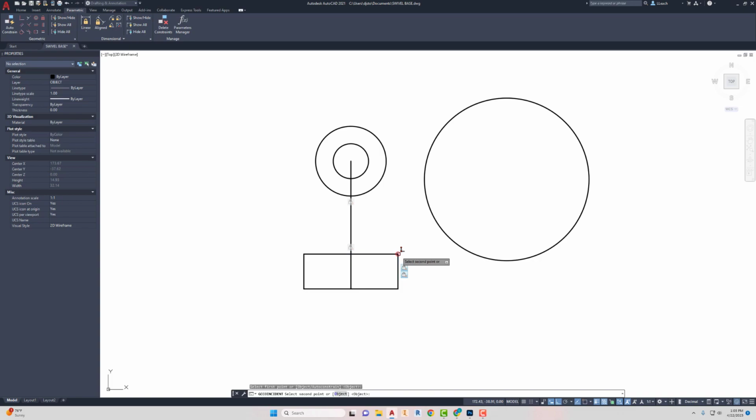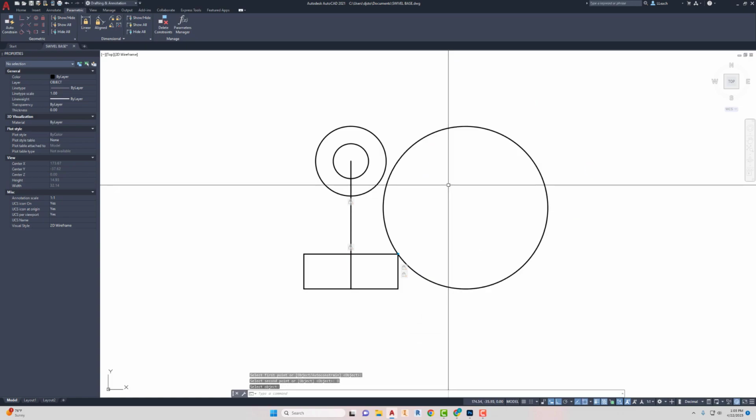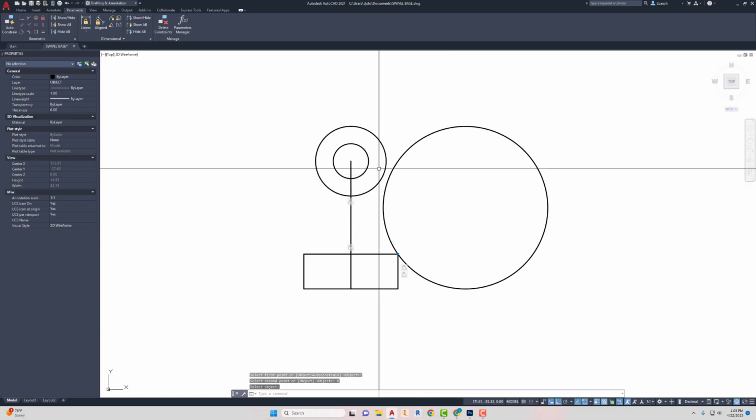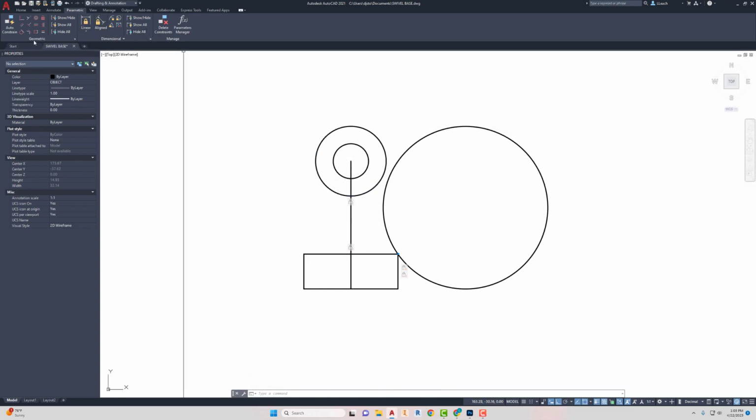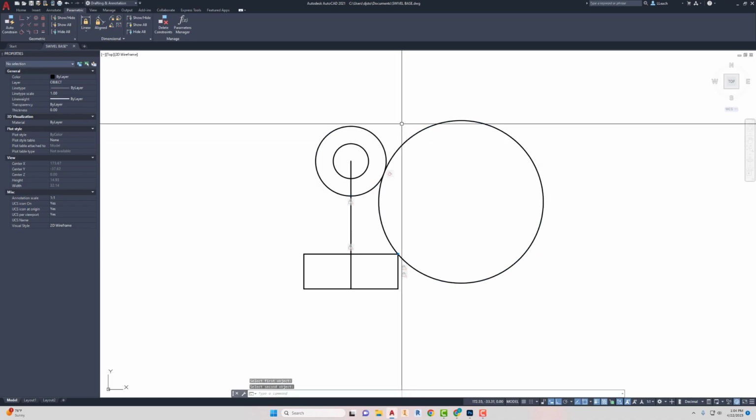That's my first point. I'm gonna click on object here, and select this circle as my object, and that slides that over. That's kind of step 1. Then I'm gonna go up to geometric constraint and hit the tangent option. I click the outer circle here, then this circle here, and we're gonna keep our fingers crossed. Boom, all right, there it goes.